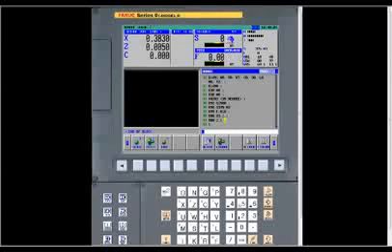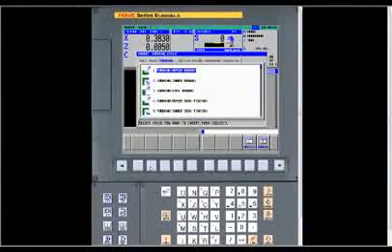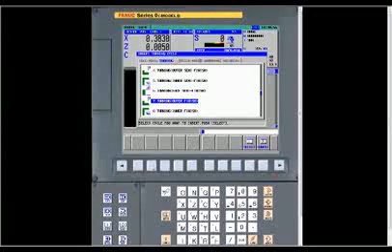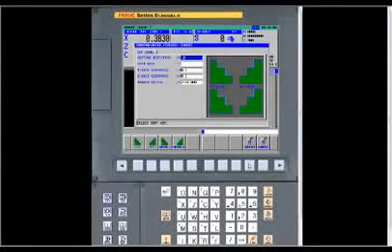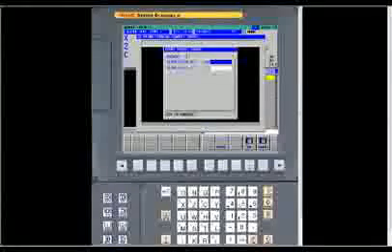We called up our cut speed. So now what we want to do is go back to cycle, turning. And now this time, we could either do semi-finish or finish, either one. So we're going to do finish. And we'll select that. And again, the finish cycle is much simpler. There's not very much to fill out for Z minus. And a feed rate, we'll slide down, enter that, then insert that.